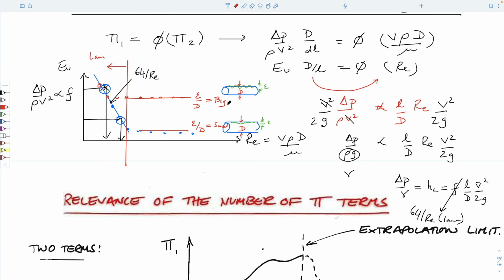And so if we wanted to figure out what the behavior is once we start going faster in the tube, there's nothing in those simple, complicated enough as they are, Navier-Stokes equations that would tell us that this behavior would happen, because this behavior isn't locked in. It's not described in those systems. The behavior that's represented in the systems is just that Newton's law of viscosity holds. So the Navier-Stokes equations assume this relationship. This doesn't conform to this.